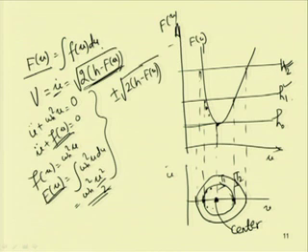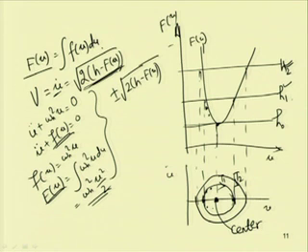of the system, by integrating this small f(u) du, and after getting this capital F(u), for a particular value of h, we can find this v. So, after getting this v, by taking different levels of total energy, we can find the flow of the system, that is, what will be the velocity of the system at a particular instant. For example, in this case, corresponding to this point we have 0 velocity, but after that we have two velocities as F(u) is less than h. So, we have two velocities and corresponding to these, we can have these 2 points.